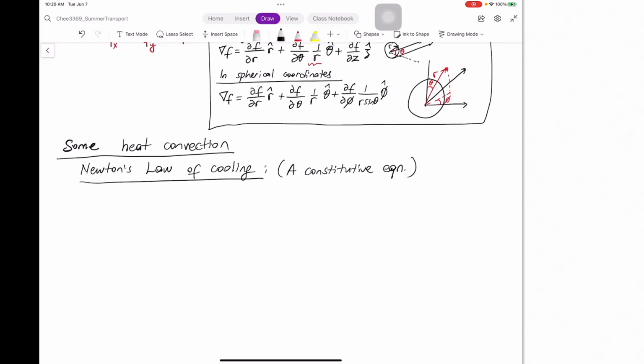or on a very crude model instead of having a fundamental reason behind it. For example, the energy conservation equation is not a constitutive equation. It's a fundamental equation and fundamental law. Newton's law of cooling or Fourier's law, on the other hand, is a constitutive equation. It's just a model. It might not be valid for one material, but it might be valid for another material. So it might depend on your system. So when we say constitutive equations, it's just a model, generally empirical.